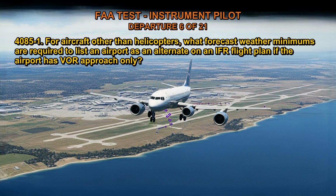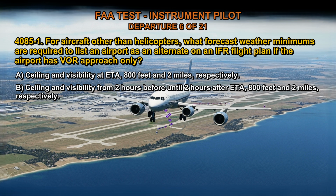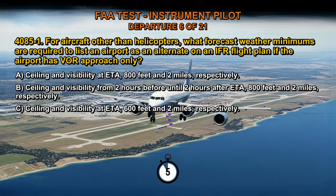4085-1. For aircraft other than helicopters, what forecast weather minimums are required to list an airport as an alternate on an IFR flight plan if the airport has VOR approach only? A. Ceiling and visibility at ETA 800 feet and 2 miles, respectively. B. Ceiling and visibility from 2 hours before until 2 hours after ETA 800 feet and 2 miles, respectively. C. Ceiling and visibility at ETA 600 feet and 2 miles, respectively. The correct answer is A.